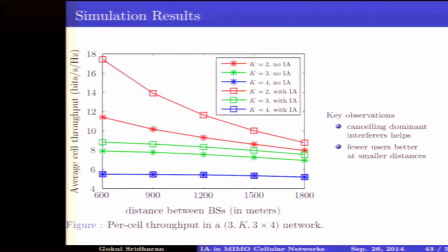But if I were to pull in interference from other base stations, let's say I considered a large 100 base station network, and I looked at this tiny 3-cell cluster in the center, and I shrunk the whole network, then of course it would saturate at some stage. So it's getting better because the channels are getting better? Yeah, it's just that there's very little path loss, signal strength is better, so I can support higher rates.